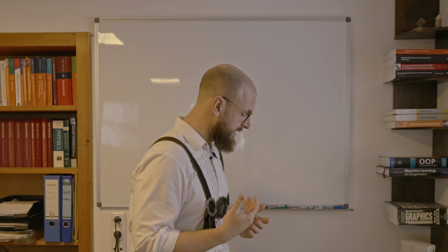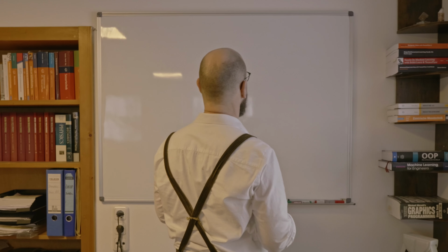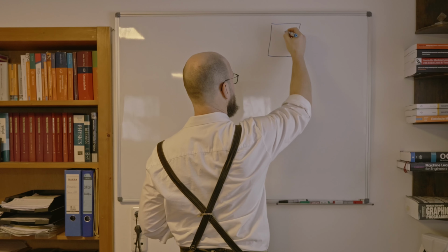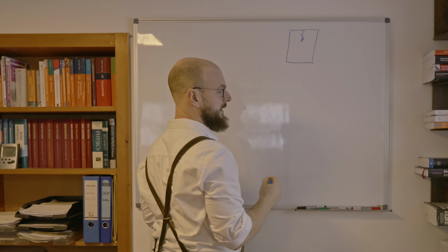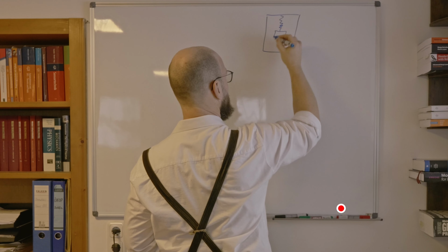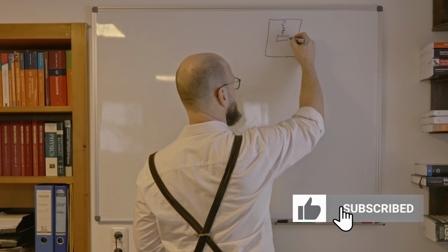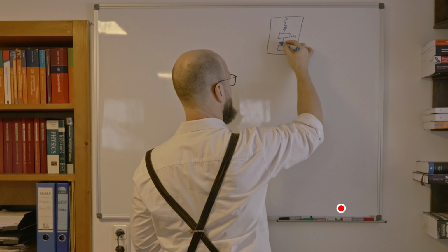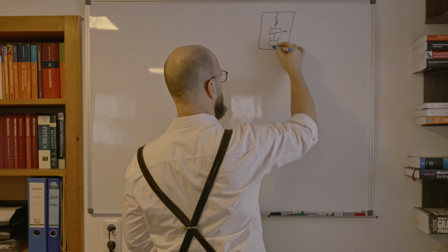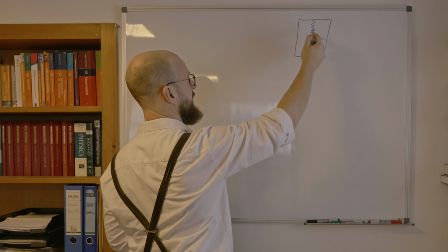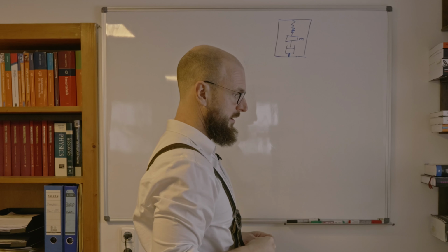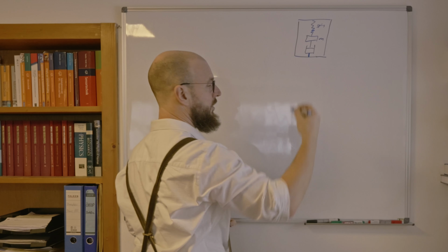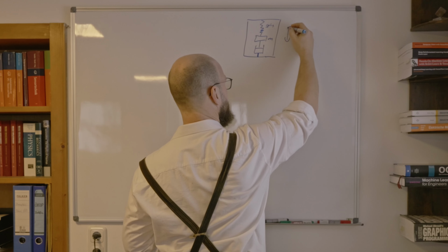How to do so? The typical idea is we use some inertial mass. So let's imagine our sensor, which has some strain over here, coupled to our mass m, our inertial mass m, and somehow damped in a certain way. So that's the damping. That's a normal spring. Imagine that's a spring the mass is connected to. And now we just consider movements in that direction.